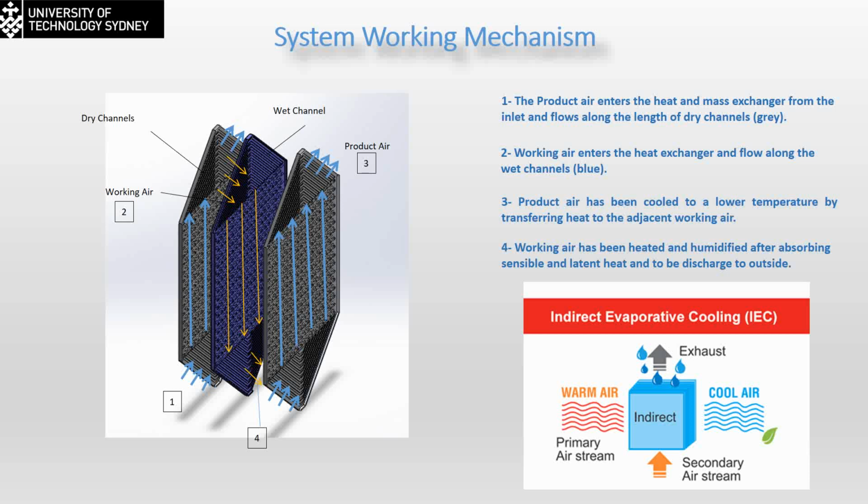On the other side, the plate wall is going to have a water layer. We're going to have the return air coming from the building, which is cold air actually, passing through the water film, cooling it down, and thus cooling down the plate, and thus increasing the heat transfer rate with the primary air before we supply it to the zone.